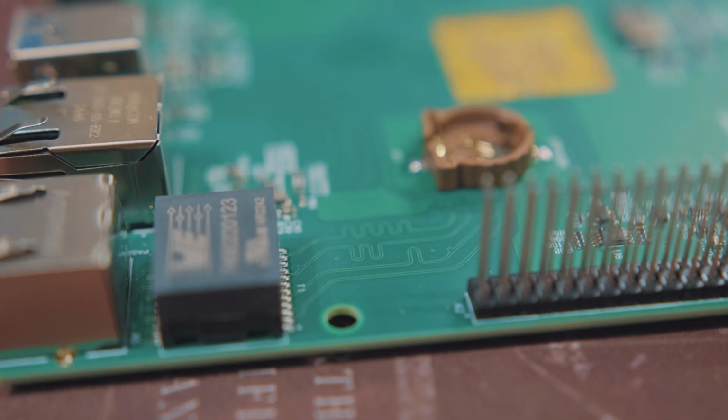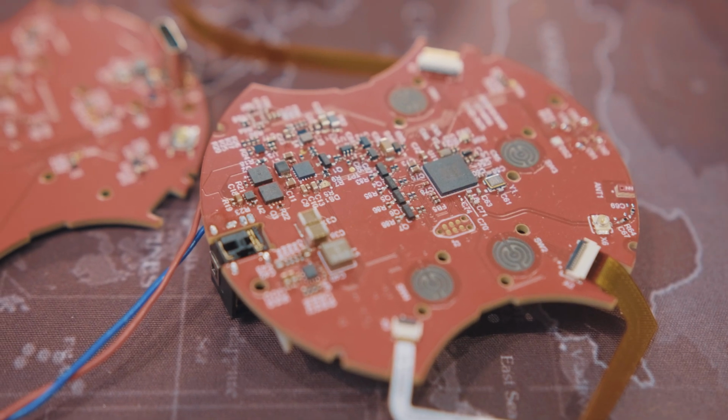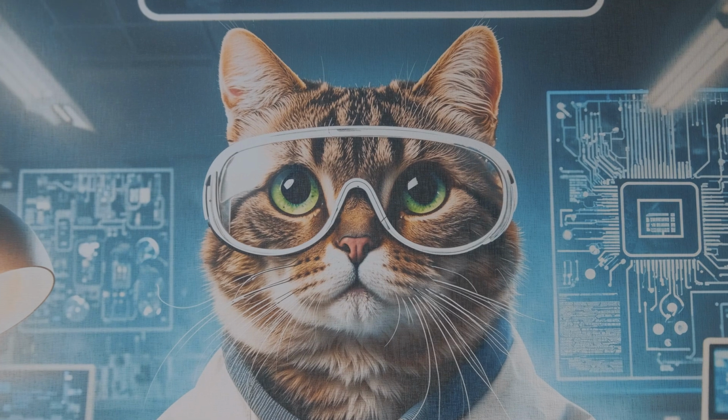And don't forget to use impedance calculators or controlled impedance tools in your PCB software. Even small changes can lead to signal integrity issues in high-speed design.